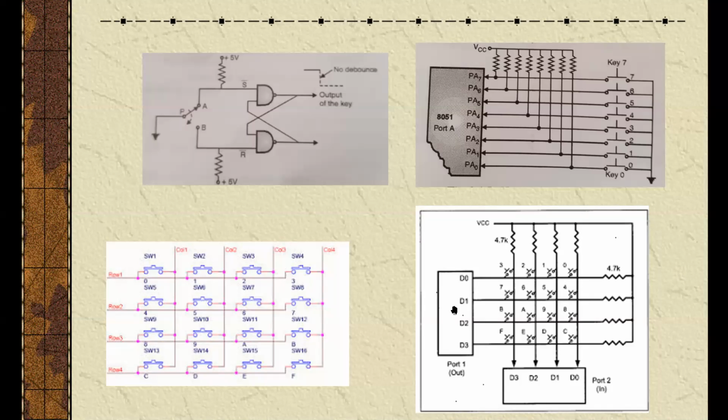Then all the keys in the keyboard matrix are activated. Read the status of the rows, that is the return lines. If the status of all the lines is logic high, then the key is not pressed. Otherwise, if the status of any line is logic low, the key is pressed. So this is one way of identifying whether a key is pressed or not.